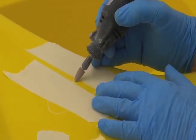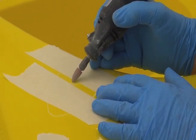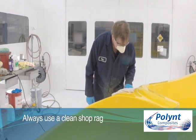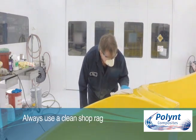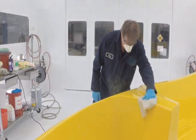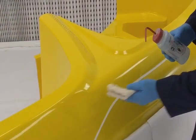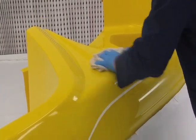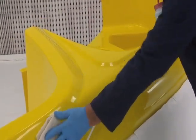Keep the area around the defect round or oval with beveled edges. Use a clean cloth to remove the sanding dust, oils, wax and other contaminants, especially when changing to a different sandpaper grit. Use a no-rinse cleaner to clean the surface and always read the MSDS before using any chemicals.